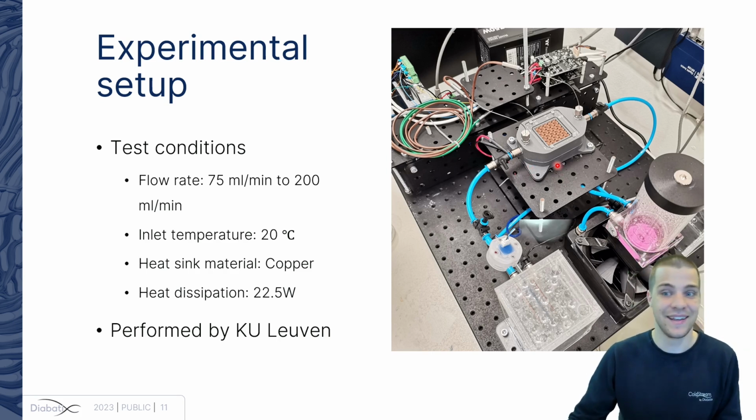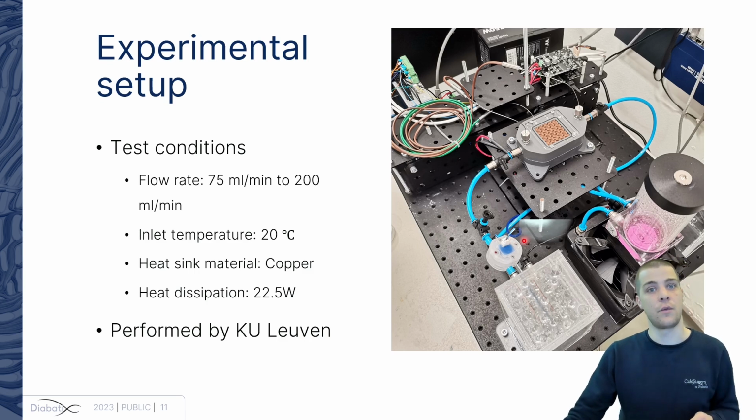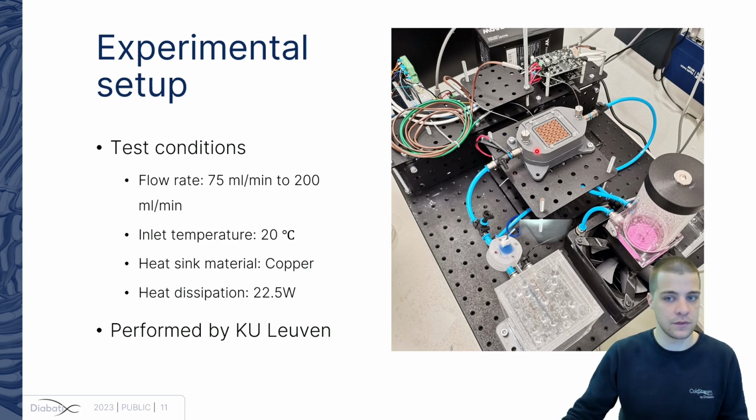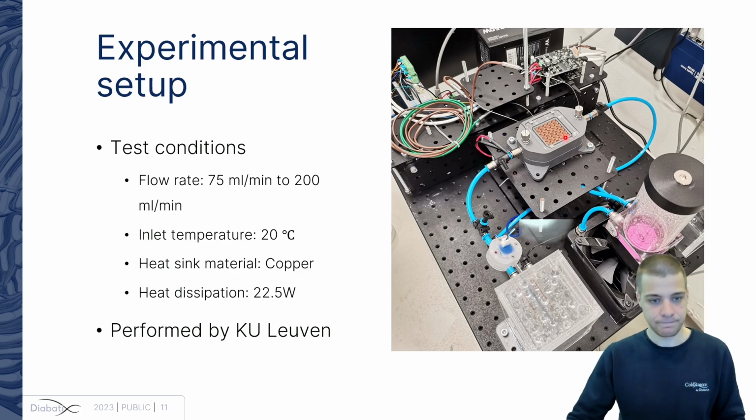The setup did account for the effort of the pump, but there are quite a bit of losses in the pipes, etc. So comparing that to just a pressure drop between the inlet and outlet ports of our heat exchanger won't have that big of an impact. That's basically the only reason why we didn't look at the pressure drop.